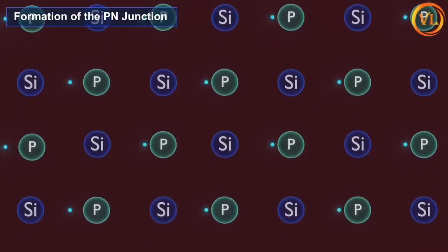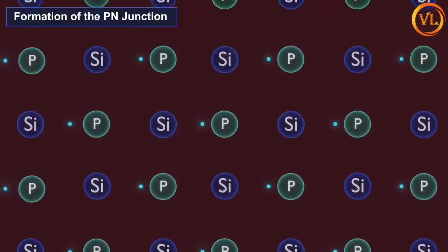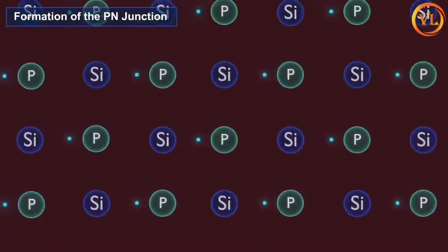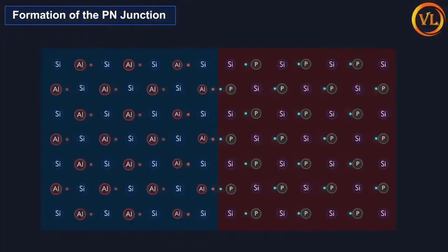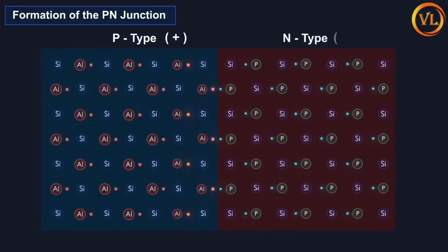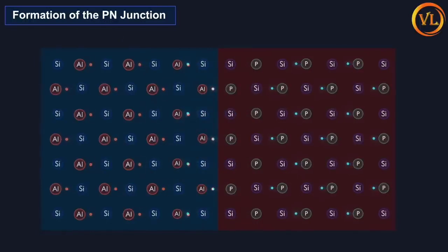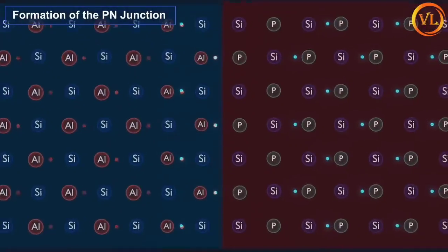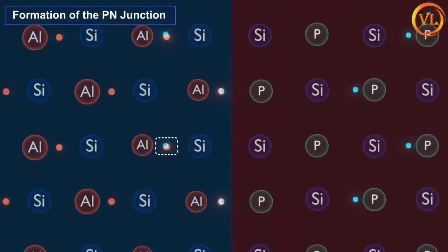In a semiconductor doped with a donor, a free electron is now present, and donor impurities donate a negatively charged electron to the lattice. So a semiconductor that has been doped with a donor is called an n-type semiconductor. N-type stands for negative. Free electrons outnumber holes in an n-type material, so the electrons are the majority carriers and holes are the minority carriers.